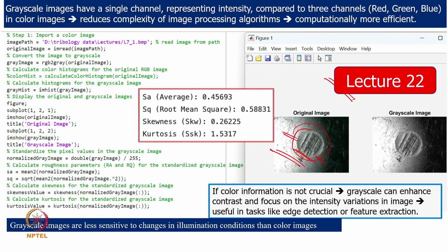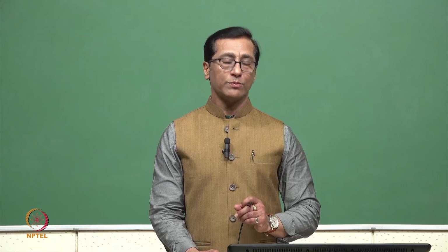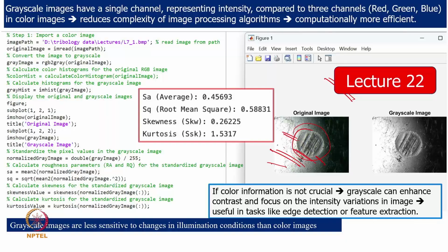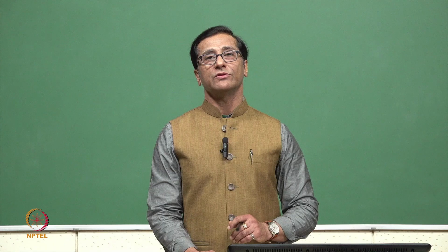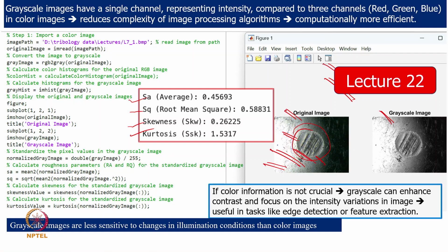And one more thing, as I mentioned, when we were doing this in 2009, this kind of technique was not very popular. Now those techniques can be brought in. Take an image of those failed bearings again and do the analysis. Take the original image, go to the grayscale image, convert to surface roughness parameters, and account for those parameters in the film thickness calculation. That will give you better results compared to what we got around 15 years back. And this was already covered in lecture 22, so you can implement these suggestions.